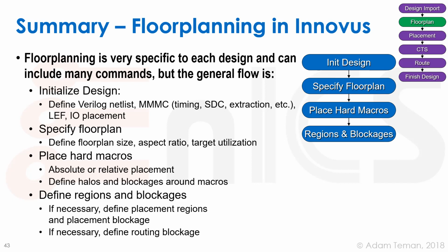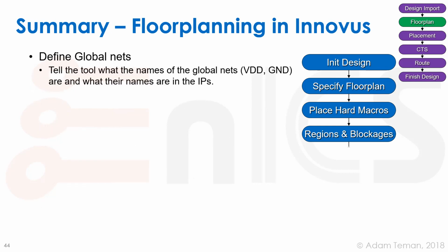Next, we're going to define basic regions and blockages inside the chip if needed, so we can define placement regions as we mentioned before, and if necessary placement blockages, we'd also define routing blockages. Next, we're going to define global nets.